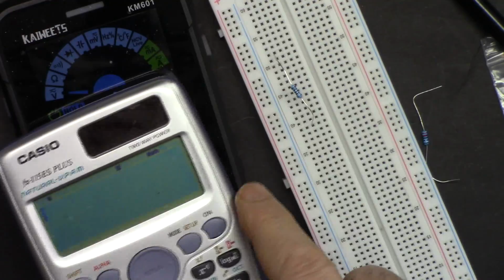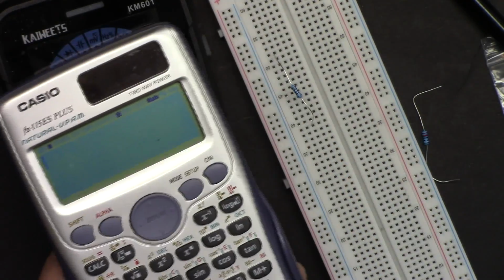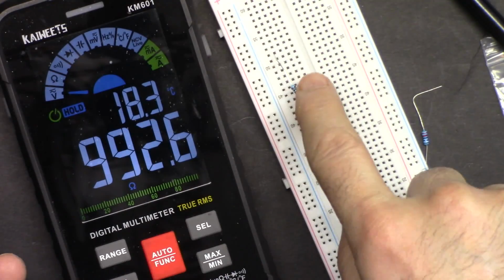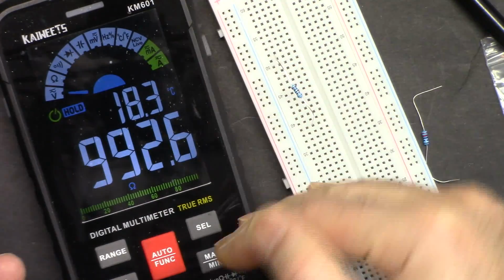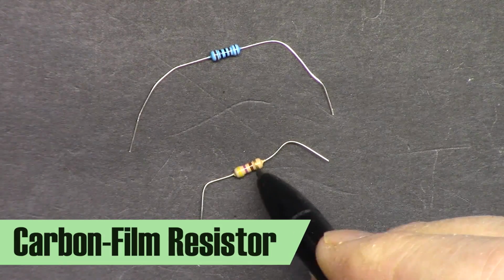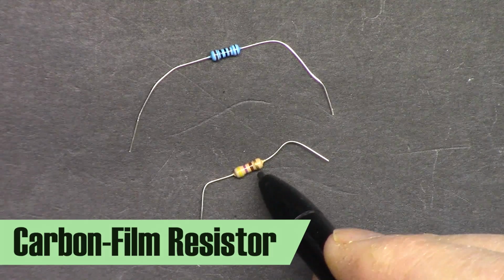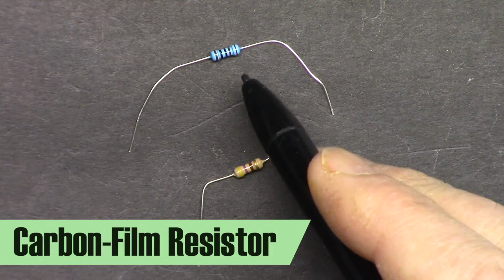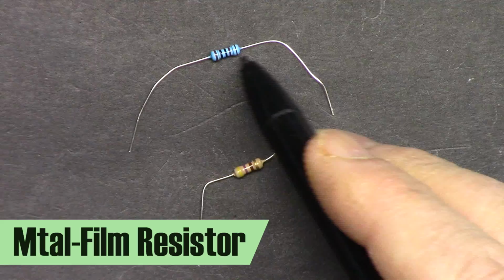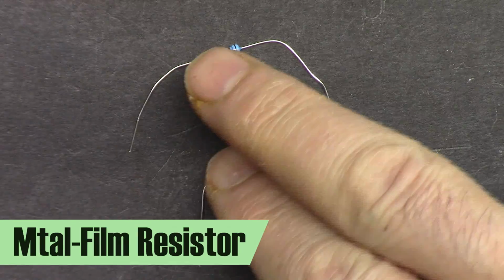Now let's check 1% of 1 kilo ohm. So 1% is 10 ohm. So this could be 10 ohm high or 10 ohm low. When you see something yellowish or beige, this is carbon film, usually 5, 10, and 20% tolerance, and this is metal film, usually 1% or lower tolerance resistors.